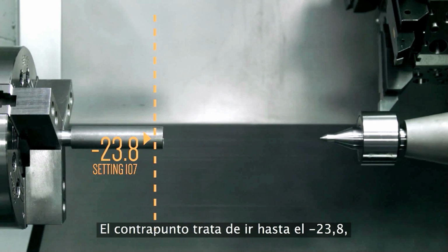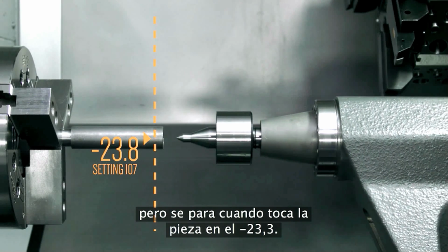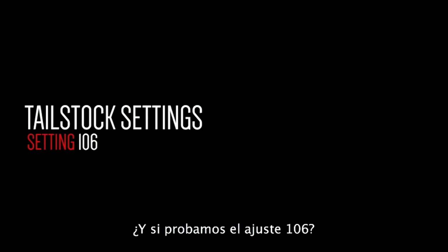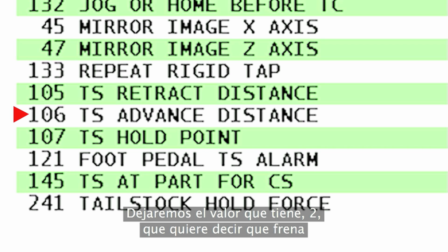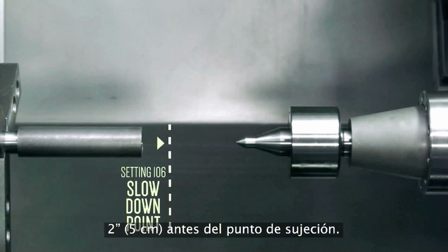Let's test our new 107 value. The tailstock is trying to reach negative 23.8, but of course it stops when it hits the workpiece at negative 23.3. Great, the part is clamped. How about setting 106? This setting tells the tailstock when to slow down from rapid motion. We'll leave it set at its present setting of 2, which slows motion 2 inches before the hold point.